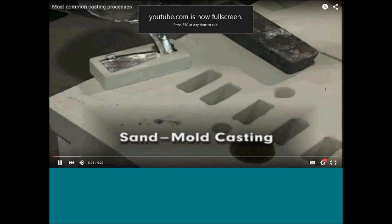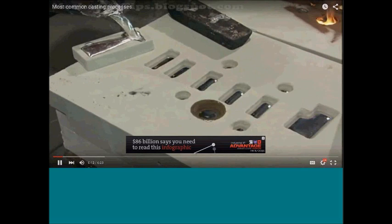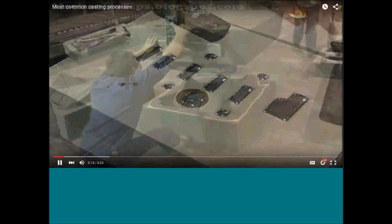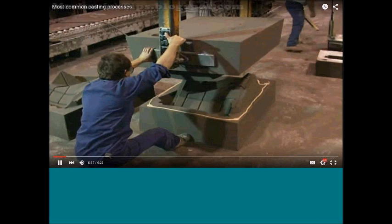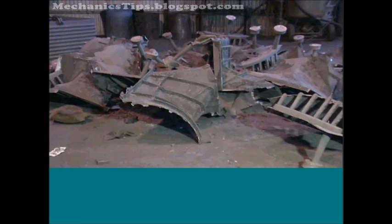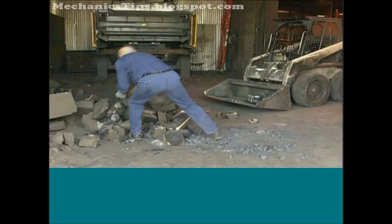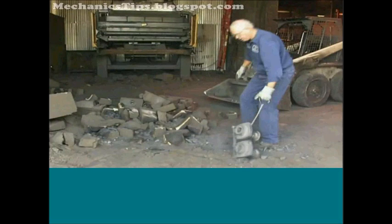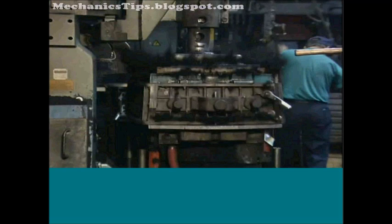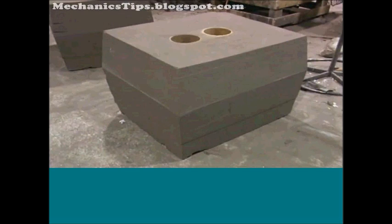Sand mold casting, also called sand casting, is the most common casting process. It is applicable to a great variety of metals, and there is essentially no limit to the size of casting that can be made. Castings made in sand molds are not very precise, but production cost is generally lowest. Although the molds are expendable, the sand can usually be reconditioned for reuse. Sand molds, made in halves, are built by tightly packing the sand around the pattern in a flask. The upper mold half is called the cope, and the lower half, the drag.